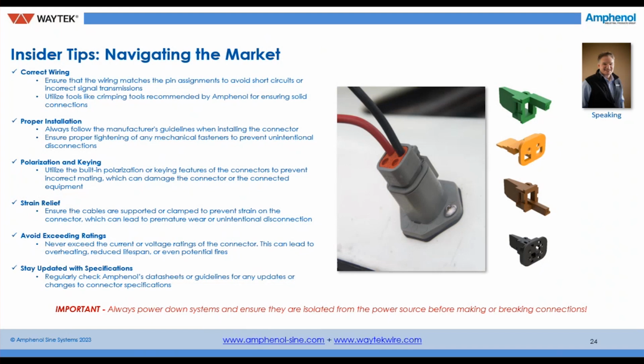Strain relief would be another one. When we think about strain relief, we have strain reliefs that go on the back of it that are going to certainly help with the IP rating. We've got a slide to show you that a little bit later, so we'll save that for more there. Avoid exceeding ratings. Well, there's a great tip, right? If a connector is rated at 13 amps, you certainly don't want it in an application that's more than that. Temperature, as we've talked about, IP rating, make sure that we're matching the connector for that particular application.